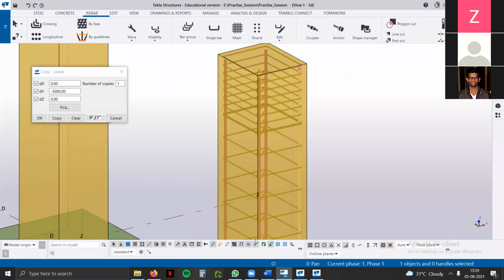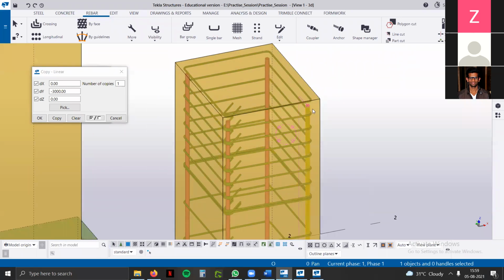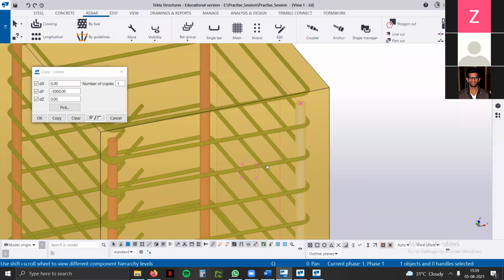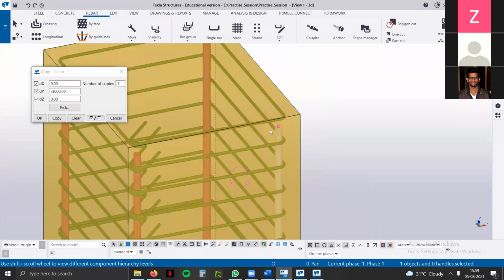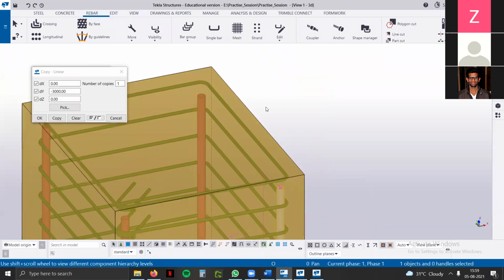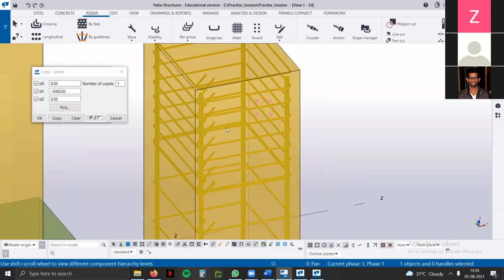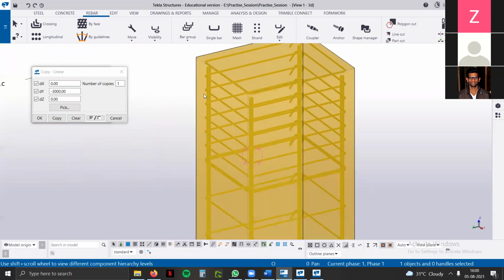These are individual. Since I select objects in component, I had to select one bar. I had to use this option because I had added another part in it, like another component used in this particular concrete element. So it's acting as a whole component. If I choose rebar in the component, I'll use that part.